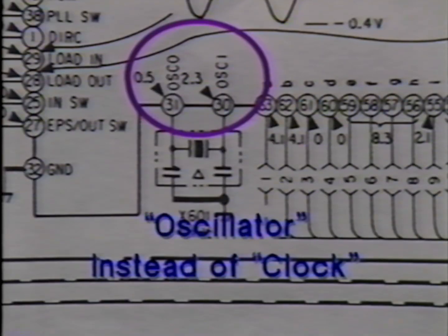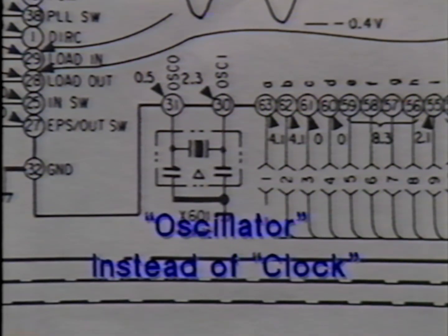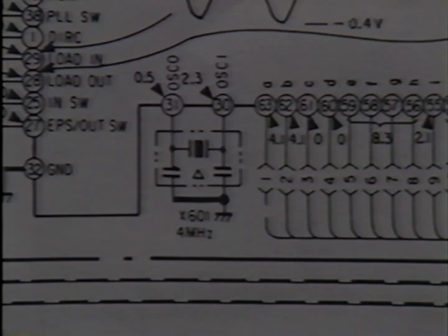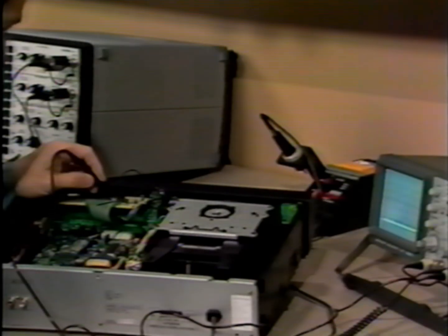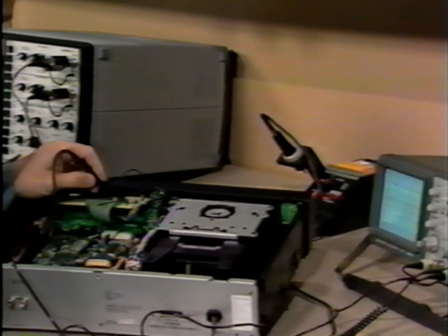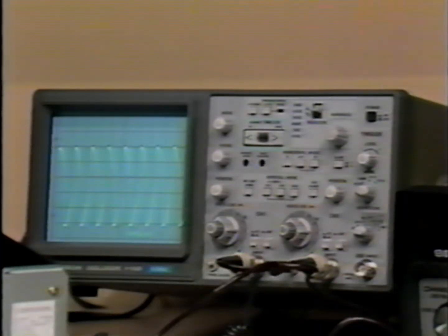This is a fairly common practice that allows the clock label to be used for the signal used to coordinate communications between the microprocessor and other system components. One side of the microprocessor clock can generally be observed on the oscilloscope. Occasionally, the oscilloscope will load the crystal and swamp out the oscillator.